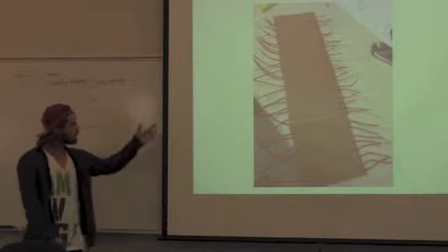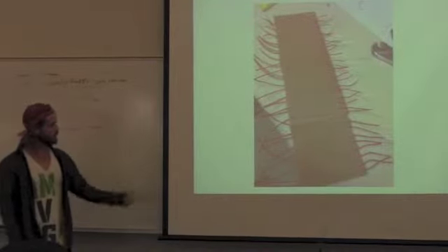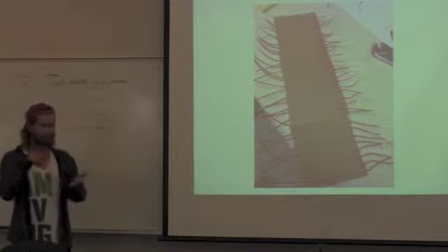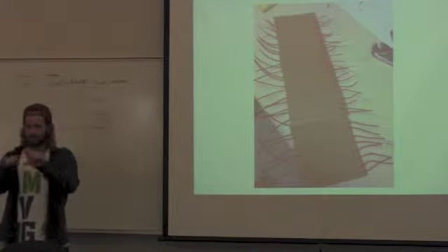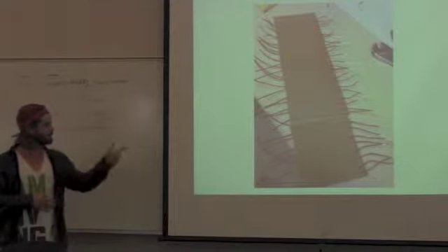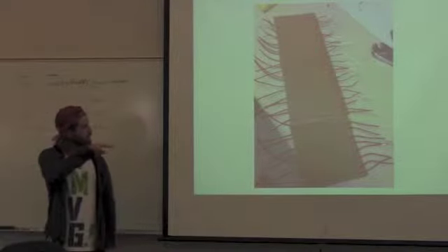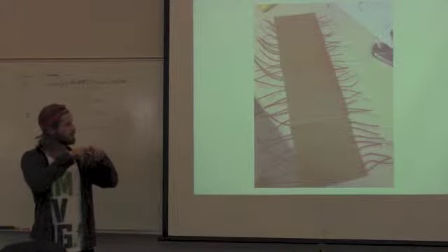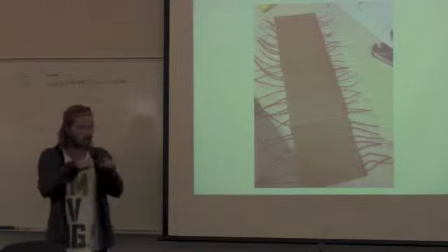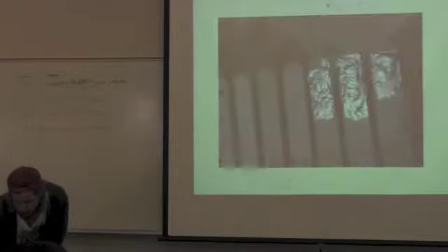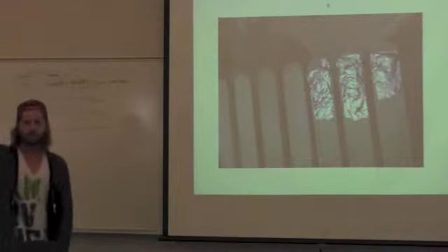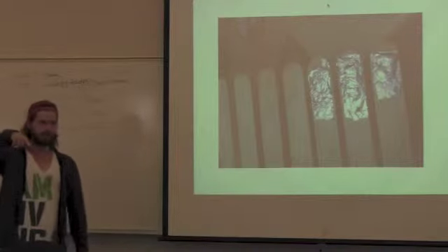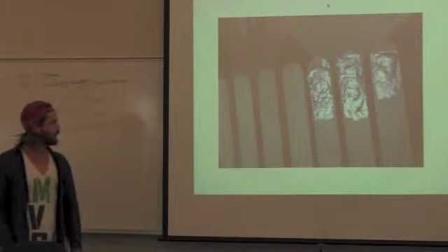So to look at how we made our keyboard, it turns out cardboard's really good for running wires because it makes it pretty clean and it's got little lines, perfect for the wires to go through. What we decided to do was make an open circuit right there with 2 wires, stripped to make pads right next to each other. Then we use tongue depressors I got from the health center. You just put aluminum foil on the bottom of that, and as soon as you push it down, it creates a short, and they become an active high button.